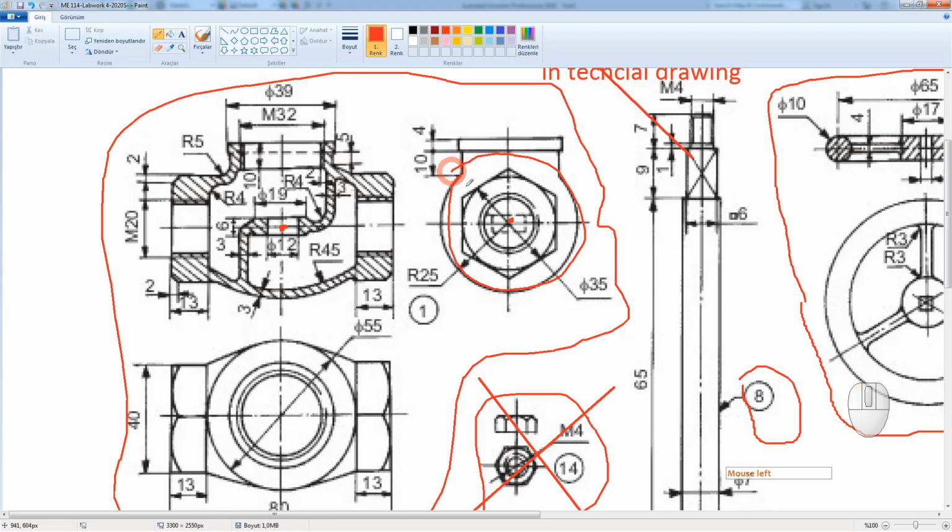At this point, when we have drawn our midsection here, we need a pathway to define our loft process, and this path must pass within the 3 sections which we are going to draw.